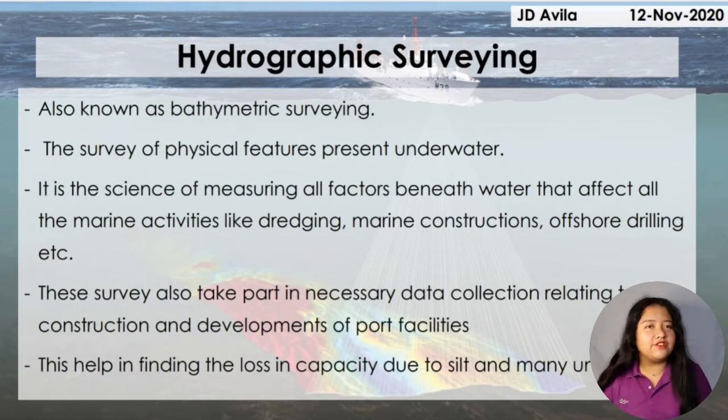such as pier construction. So, hydrographic surveying is, as what it defines, the surveying of what is beneath the underwater. For planning and constructing causeways, bridges, and offshore platforms, it is often necessary to conduct a hydrographic survey. These types of projects require special procedures to solve the problem of establishing horizontal positions and depths where it is impossible to hold a rod or a reflector.